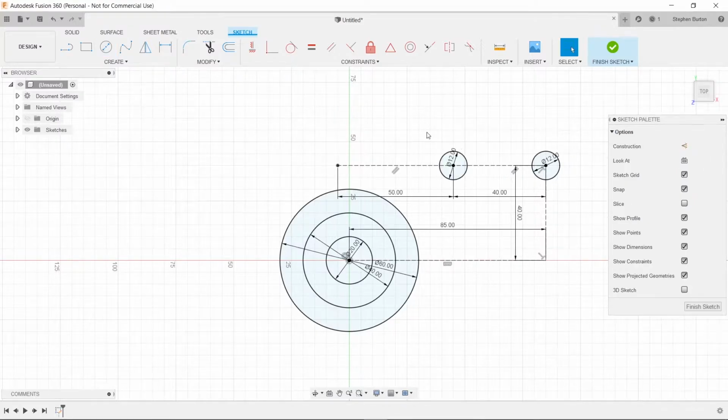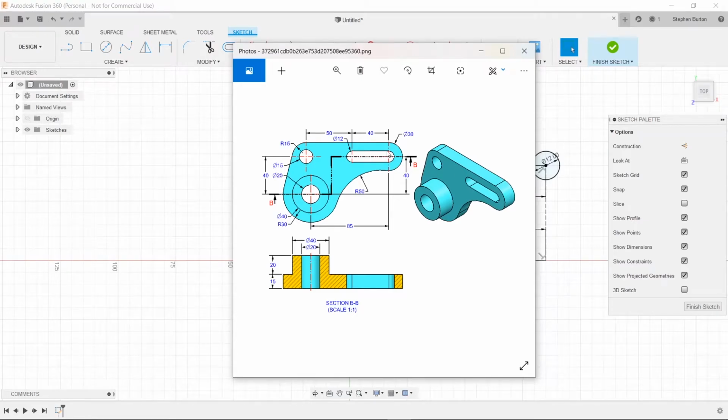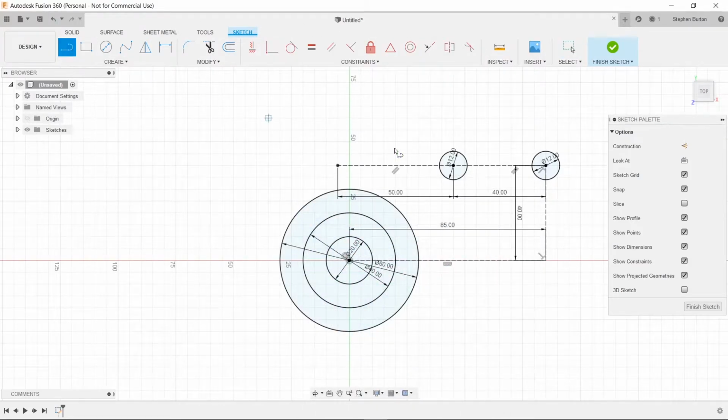Now with circles, with this kind of drawing here, it's actually pretty easy to get the line to be tangent. All you have to do is make sure that you highlight the upper corner, or up in the middle top, and it will actually latch to it. So we'll do that now. We'll click on line here, and we'll go down here and select and click. And then we'll do the exact same thing, see how it snaps to that upper portion, and that makes it tangent. So that's nice and easy.